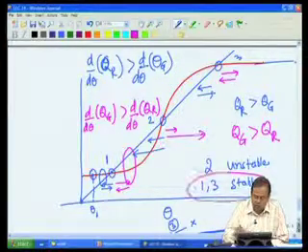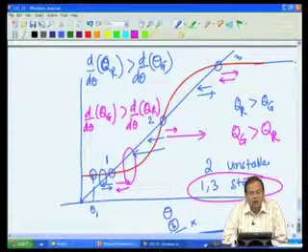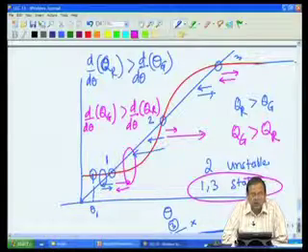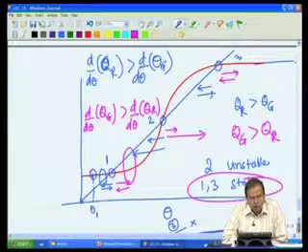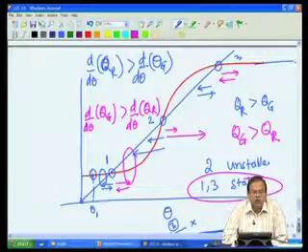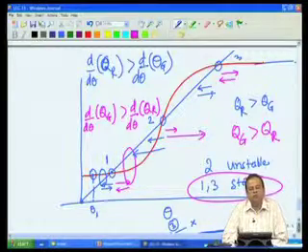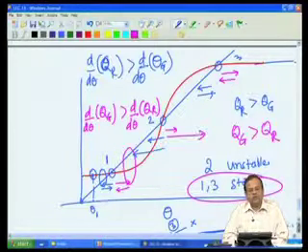So, the condition that is required for a steady state to be unstable for this particular example is that the slope of the heat generation rate is higher than the slope of the heat removal rate. We will see how this condition is obtained in a more formal way when we look at the stability of chemical reactors in our next session.